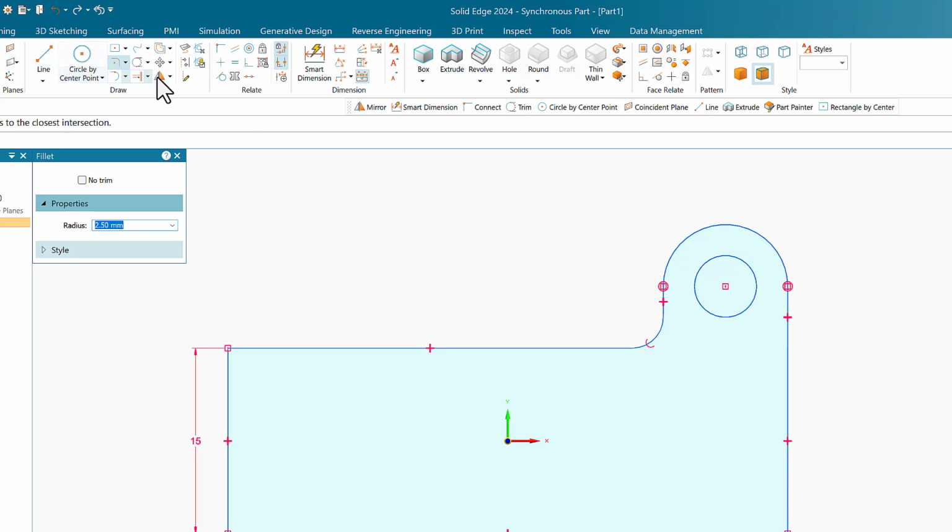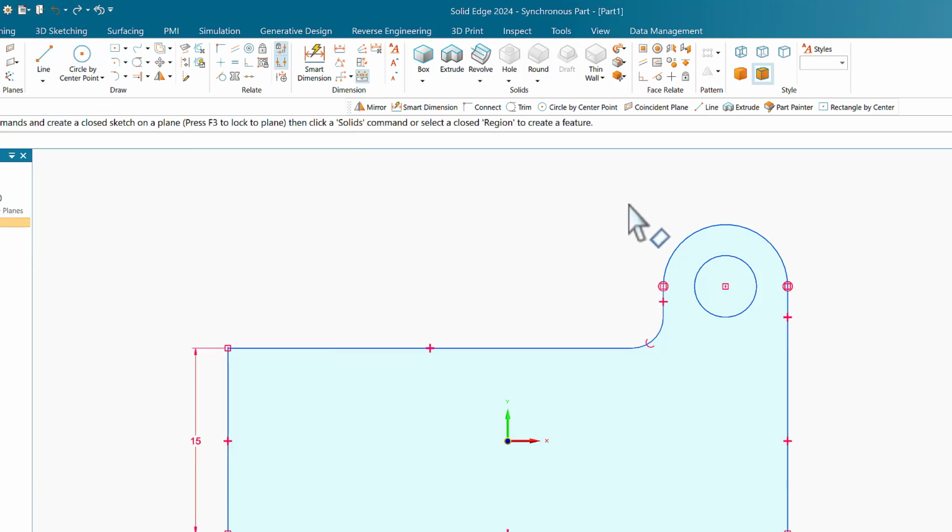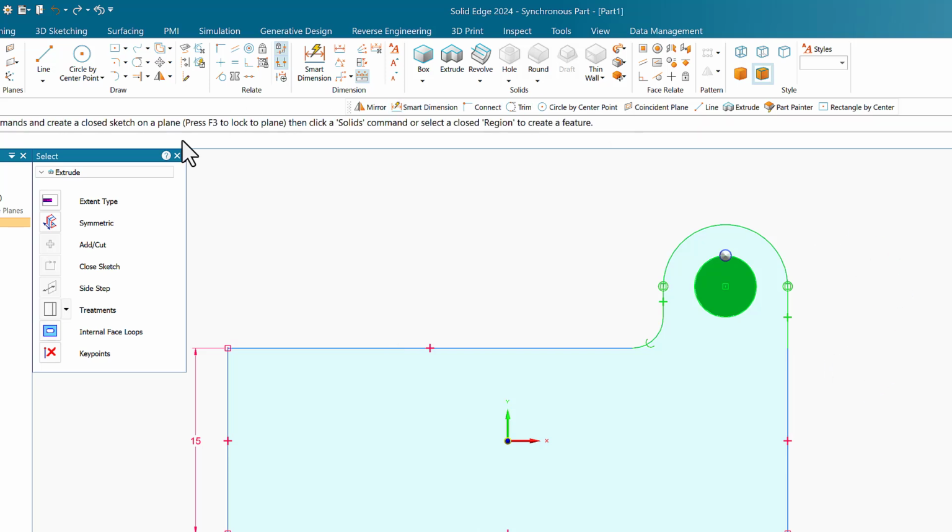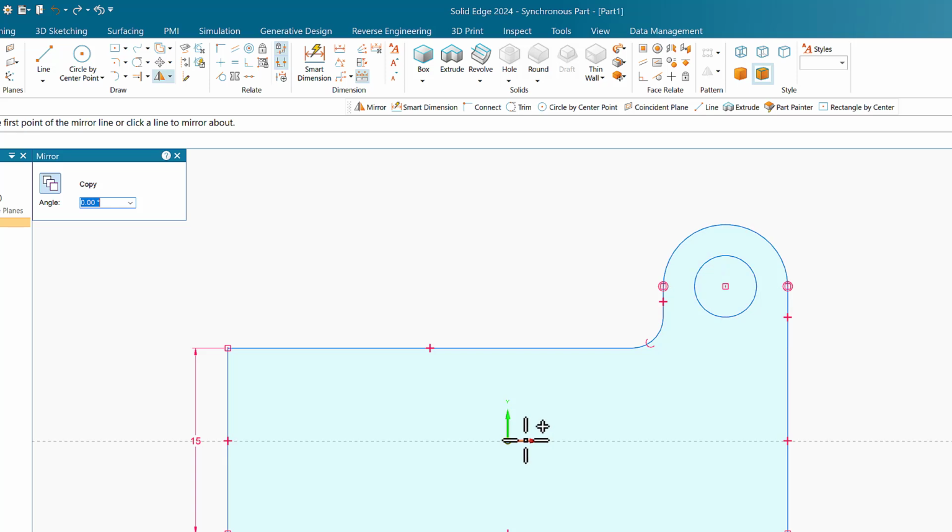So what I'm going to do, I'm going to use mirror to repeat this thing to the bottom part. Okay, so I'm going to select, highlight this part only, and make a mirror around the x-axis. Click. Very good. Okay, click again so you can get out.